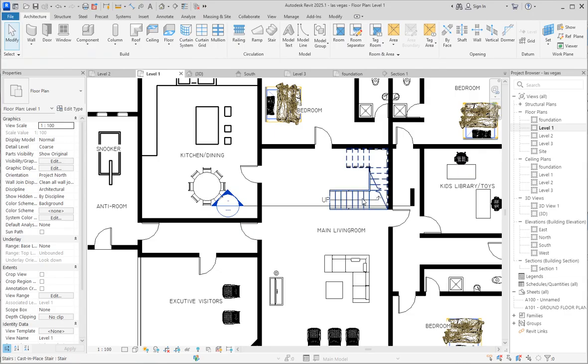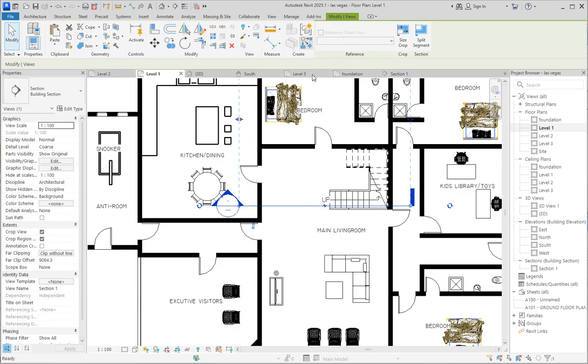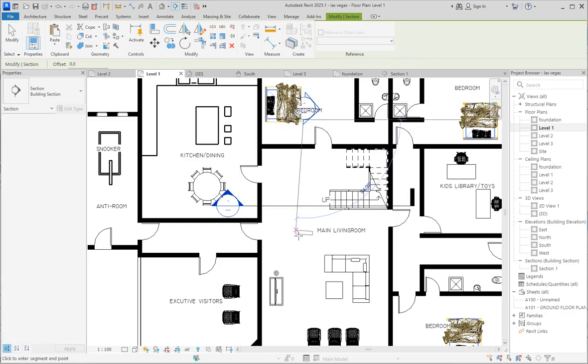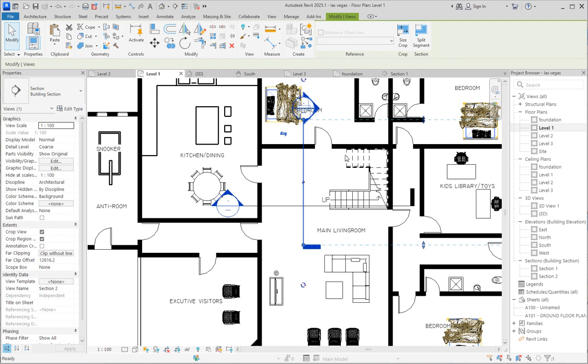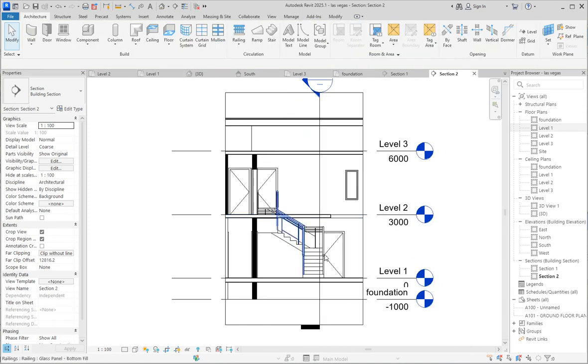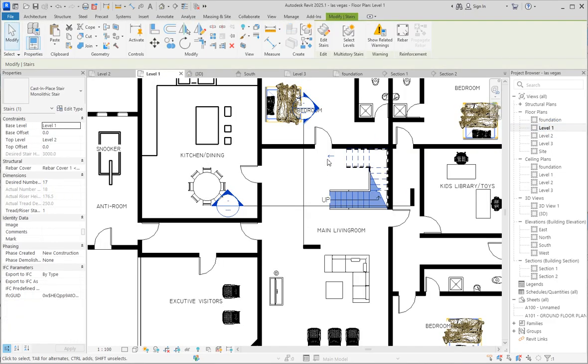So if I have it there, I can decide to manipulate by changing my stair the way I want it to be. So what do I mean by that? So click on this one and say duplicate it. Let's make another section that faces. Go to view. So we have another section that faces this place. So if I want my stairs to start from this side, I can do it. If I want it to start from another side, I will do that. So select this one now. I want it to start from another side. So go back here and you say flip.